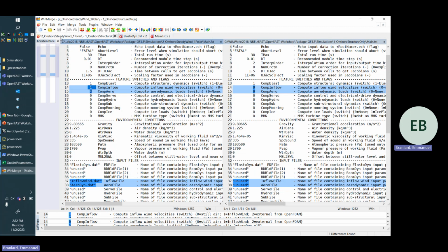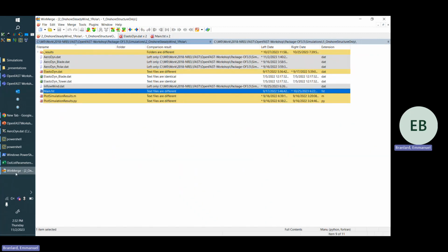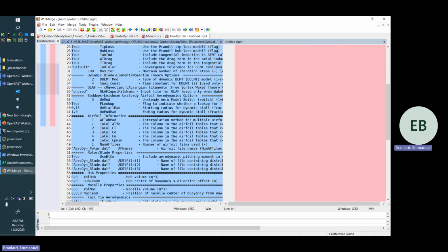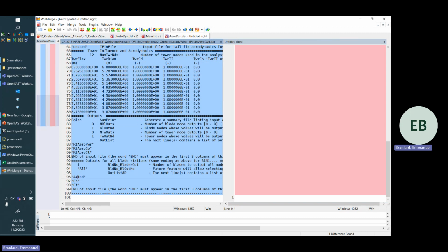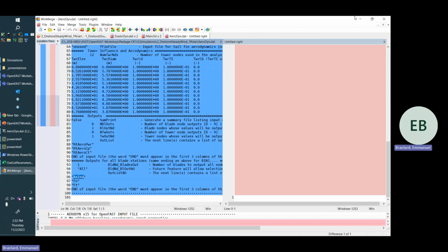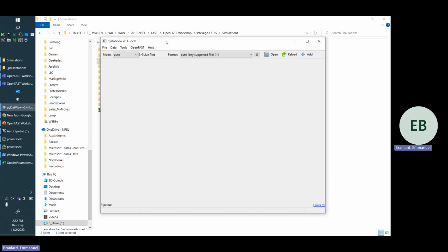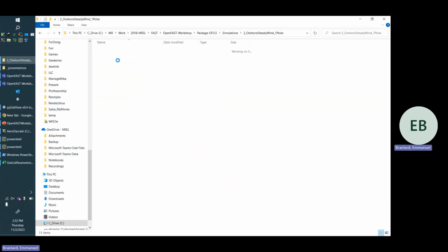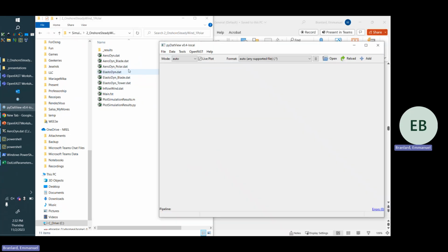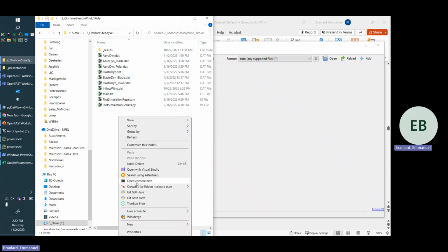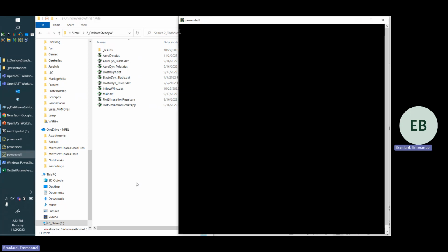I'm going to move forward to the next case. What's important here is now we have aerodynamics in the output file. So at the end of AeroDyn, we have set up actual induction to be there as a nodal output. Now I'm going to start using this PyDatView tool, which is what I personally use if you don't want to use Python or program each time you want to look at your outputs. So let me run the simulation first.